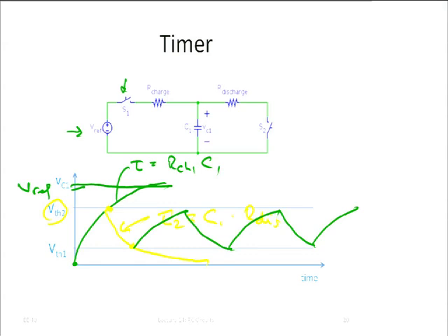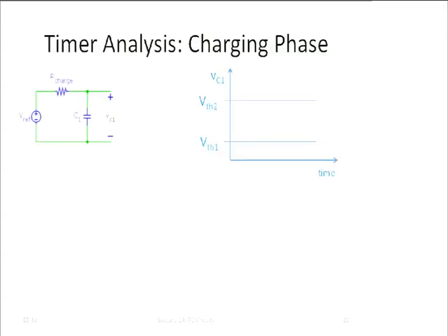So I redraw the circuit that now captures just the charging phase. I recommend that if you have any kind of difficulties or questions, do that. It really pays. It takes half a minute to redraw the circuit, but it's a lot less confusing then.